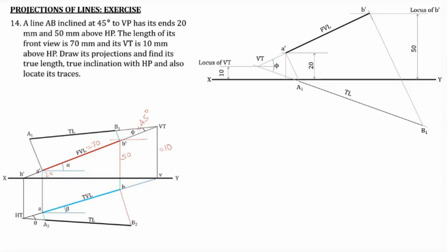Now what we have to do is, this particular distance, that is the distance of A dash from A1, or the distance of A1 from A dash, the distance that is marked with a green triangle. This distance can be taken, and that distance can be marked here, that is in the projector of A dash A. You know that these two distances are equal.